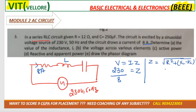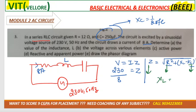Z value we obtain. R value they have given. XC we can get from C. XC is equal to 1 by 2 pi f C, right? So we know Z, only XL is unknown. XL we can get. After that, XL is equal to 2 pi f L, you can get L, right?